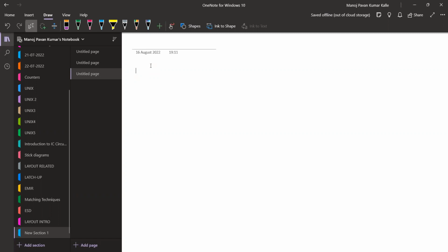Just wait, I'll come to that point. Whenever a designer comes to us and says this node has more resistance or this node has more capacitance, then if a particular signal node is seeing more resistance, we need to reduce the routing length, or increase the signal width, or go to the top level metal. You understood, right?